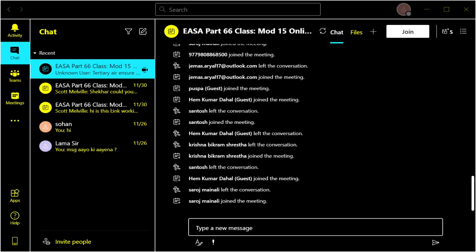So if you do pull a chip and you see something, highlight it straight away. Don't rub it on your overalls and say, oh no, it's going to cause me a lot of work, because if you do that, that potentially could cause an aircraft to crash. Okay, so make sure if you see something not normal, highlight it. It might be okay. You might just think, oh, it looks a different colour. But if in doubt, highlight it as soon as possible.